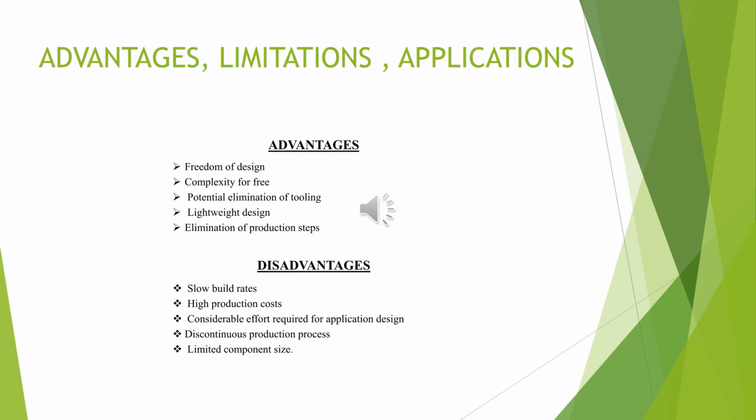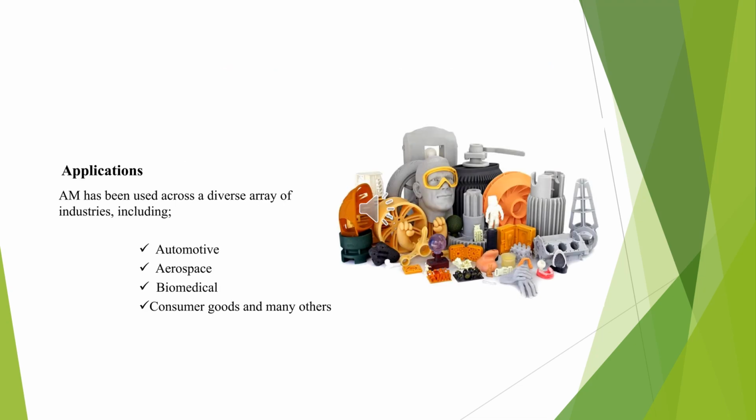Advantages, limitations, applications. Advantages: freedom of design, complexity for free, potential elimination of tooling, lightweight design, elimination of production steps. Disadvantages: slow build rate, high production cost, considerable effort for applications in design, discontinuous production process, limited component size. Additive manufacturing has a diverse array of applications in industries like automotive, aerospace, biomedical, consumer goods, and many other industries.